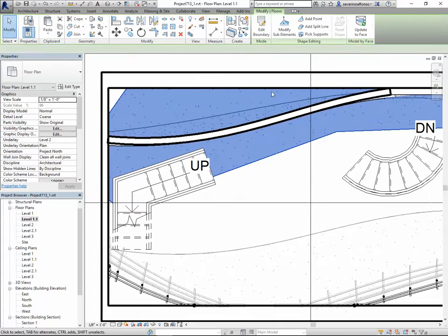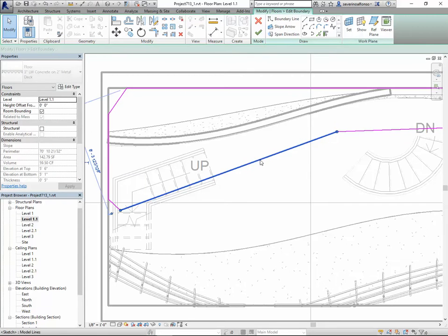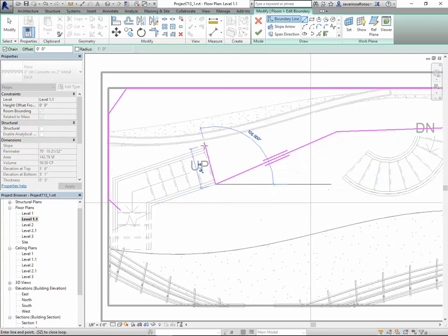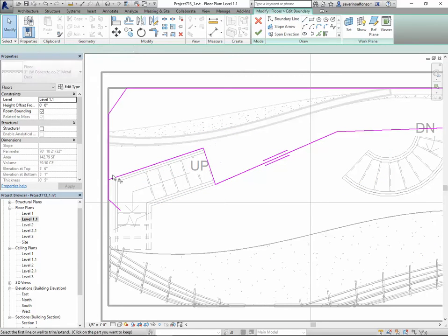And we can edit the floor plan as we did before by just very simply deleting this line and creating another one from here. Here you can even do a more fancy strategy. I'm going to trim, TR, and delete this one.